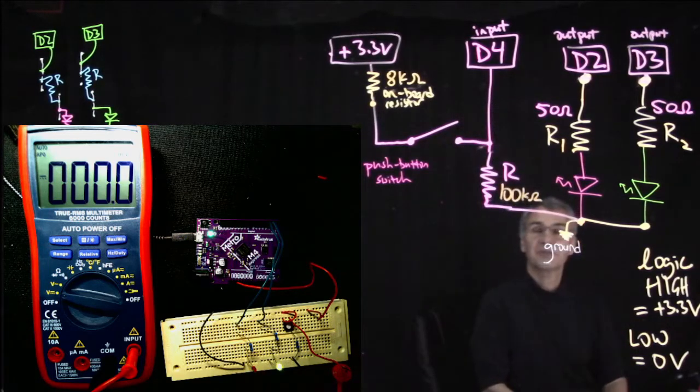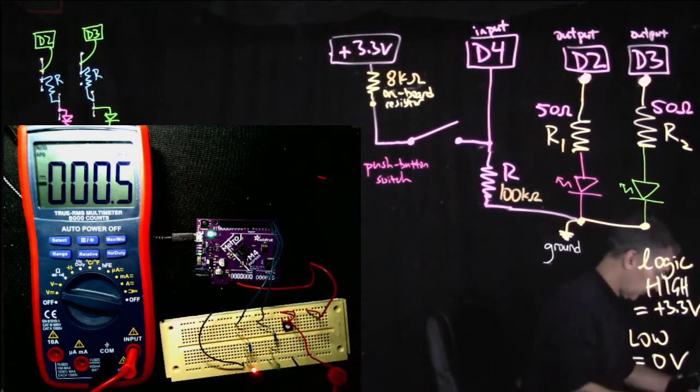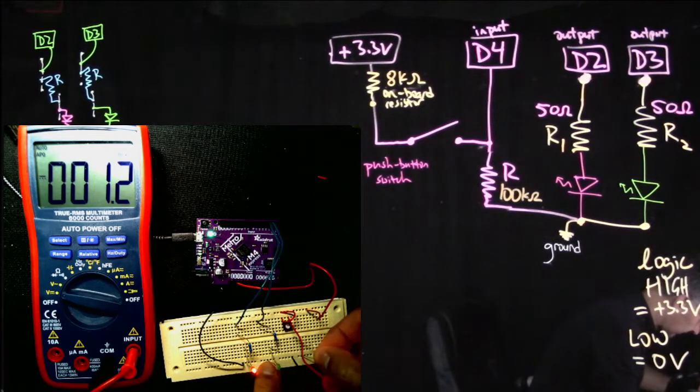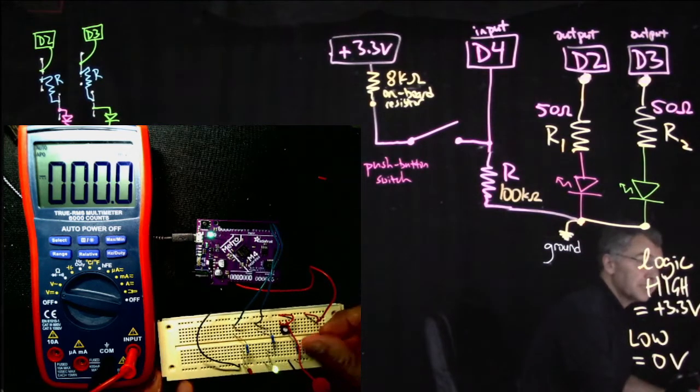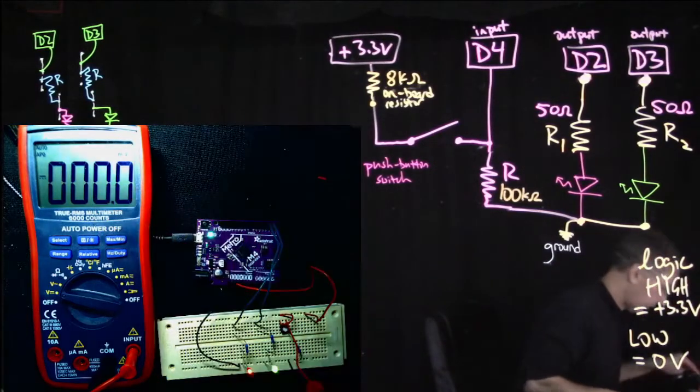Okay, this is an interesting real-life digression. So I will replace this 1K resistor with a 100K resistor. So you're watching debugging live in action. So here's my 100K resistor, and now I'm still probing that place. So I still see 0 volts if I don't push the button.